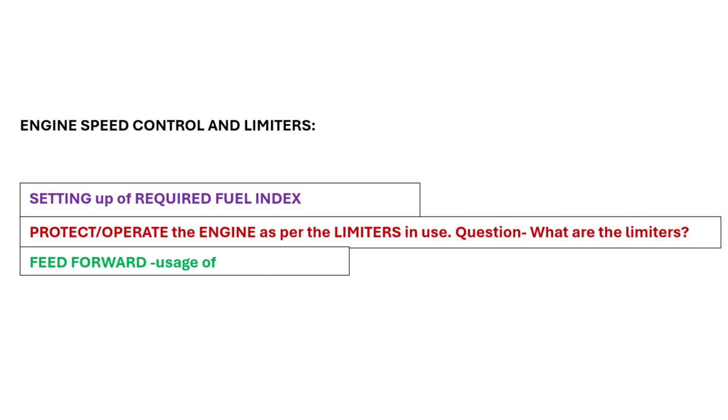If some of you have worked on large tankers, the boiler level is controlled by the level signal going to the level controller. This is the level of the boiler, and accordingly the feed pump is running continuously, so the feed valve opens or closes.